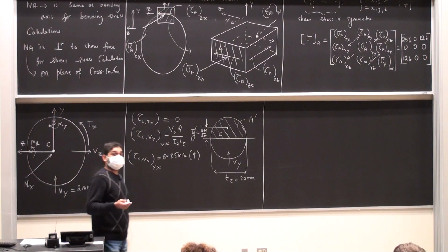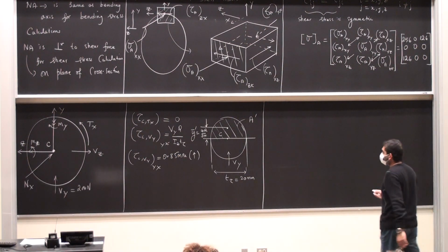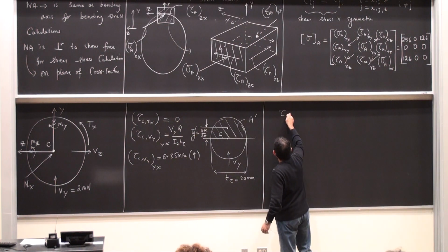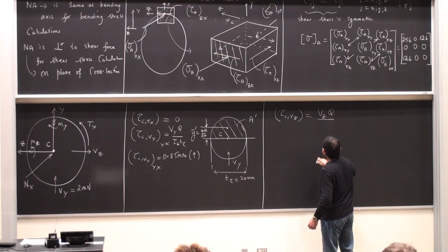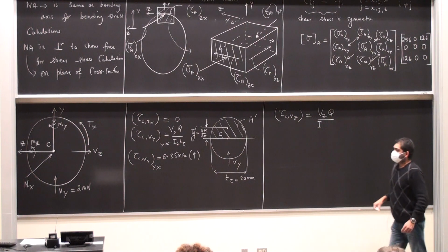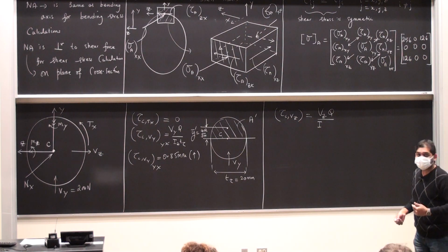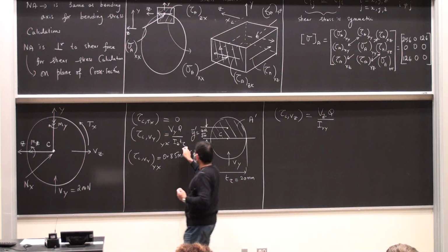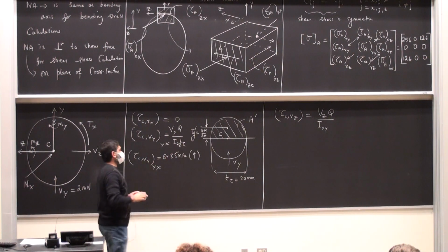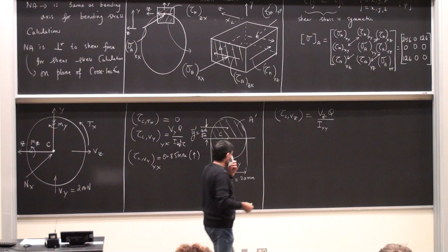I have to do the calculations due to the shear force Vz. Okay? So let's take a look at that. Tau c, Vz Q. If my shear force is Vz, the neutral axis is perpendicular to Vz, so this is going to be the y-axis, so I yy. This is Izz, I'm sorry. It's sufficient to write it as Iz, but your book writes it as a double subscript, so it's following what it says.